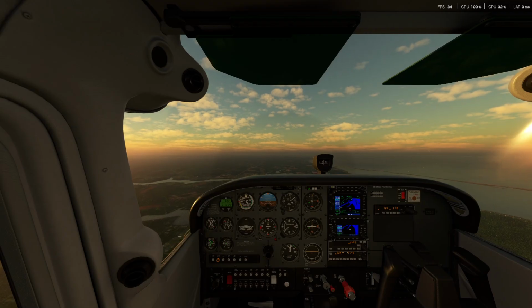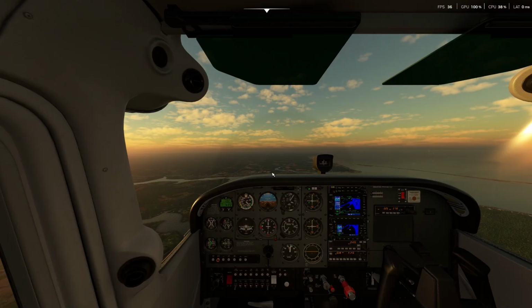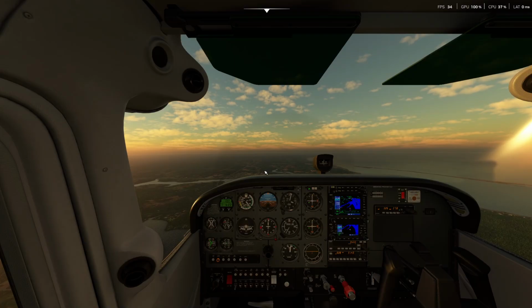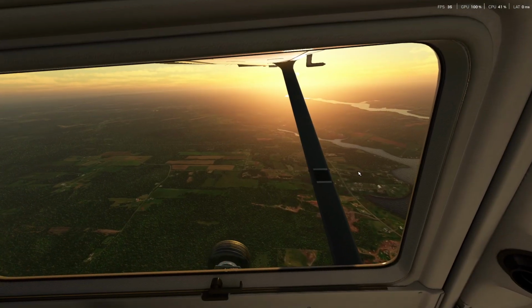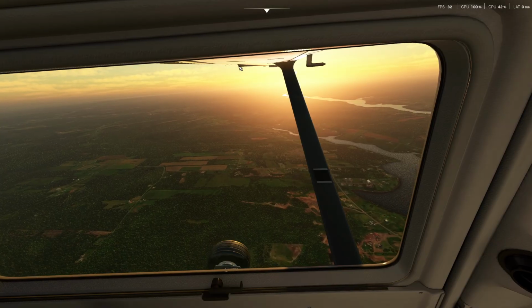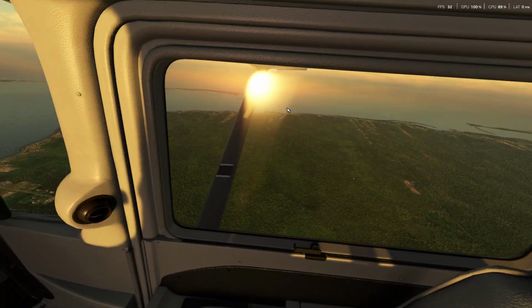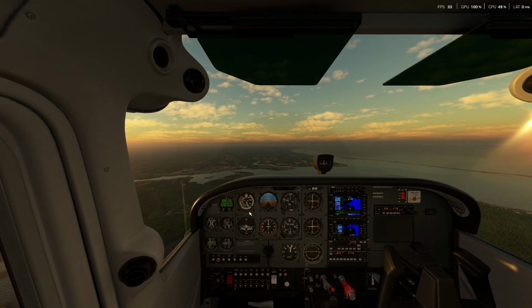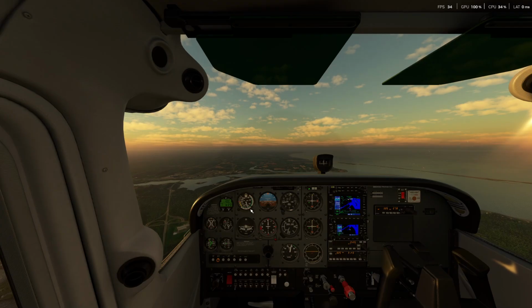So you can see when your attitude is towards the ground, you're in a descent. One common way to look at that is you can see a lot more of the ground in relation to your edge. Same thing with the left and right wing: you see the angle between the wing and the horizon, down on the left side and right side. Your airspeed has no increase right now because I throttled back slightly and I also trimmed out a bit.